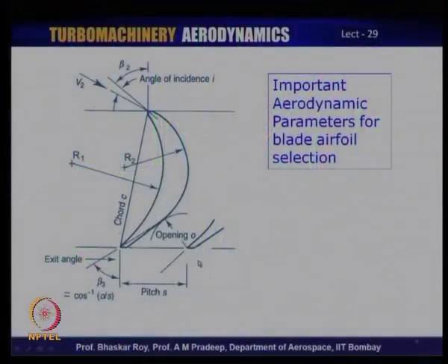And then of course, you need to decide on the opening, or more specifically the throat of the turbine passage. Now, the flow coming through this passage typically would have a converging curved passage, and it would indeed have the minimum area over here at this opening, which is often the throat of the passage. Now, the throat of the passage is of course the constriction or restriction, where the blades are deliberately designed to create an expanding flow or an accelerating flow over this blade profile.